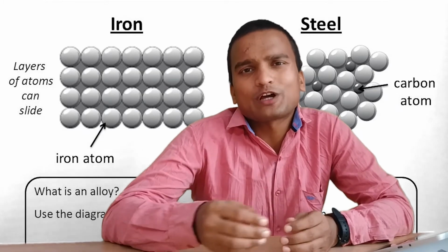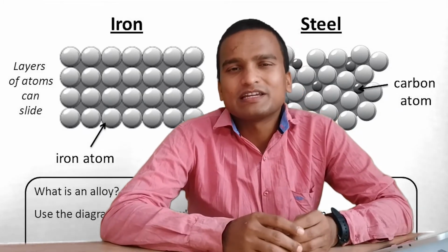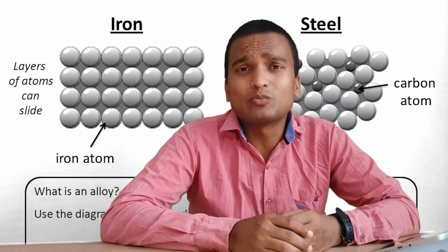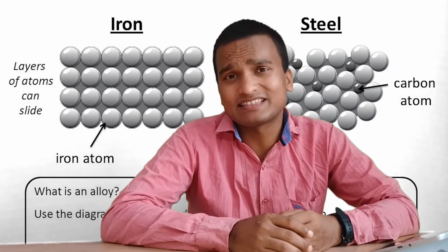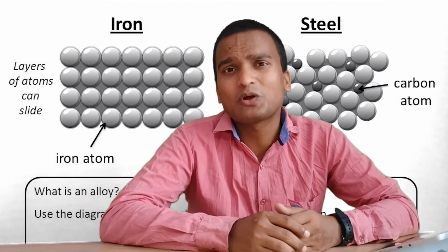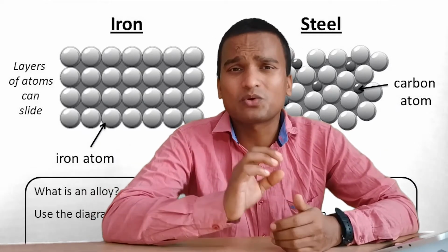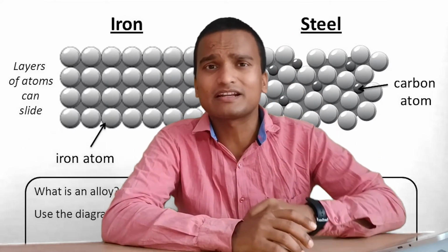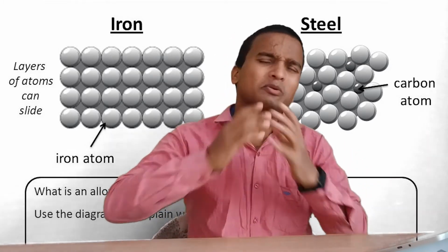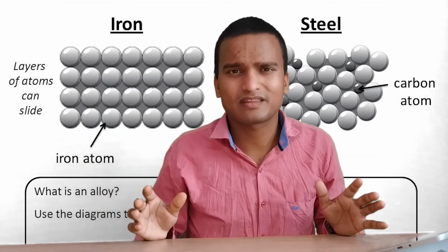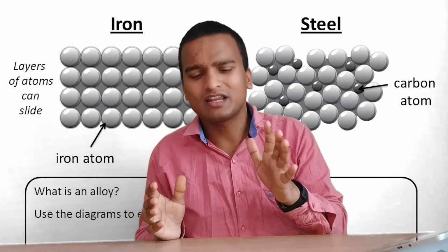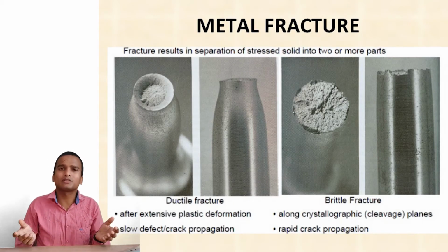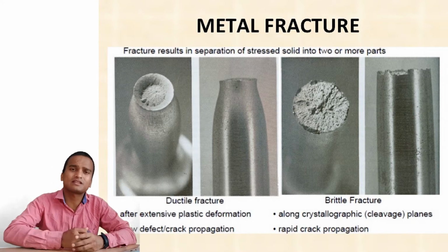Obviously, adding more and more carbon in the lattices of iron increases the distortion of the lattice and provides mechanical strength. However, the solubility of more carbon in iron lattices also has a negative impact on another property of iron, which is called ductility. If we dissolve too many carbon atoms in the iron lattice, the lattice will completely distort and go out of its shape, and if we apply some external force it will not remain ductile. And what happens if something is not ductile? It fails without giving sufficient warning, and such a substance is called brittle.